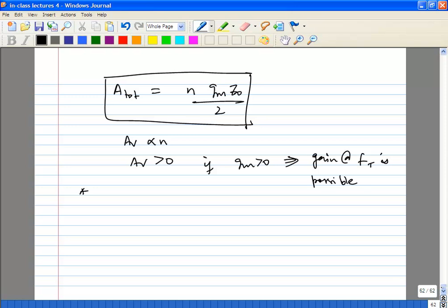Okay, so now coming to the details. Obviously, you are assuming there are ideal transmission lines. We know that. An ideal transmission line you can represent with the RLGC model, distributed RLGC, where they are all per unit quantities.